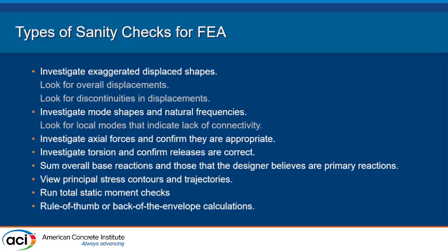Anyone who offsets a slab and has a beam frame member underneath it, there is a chord force that develops, axial force in your beam and your slab. And if you just pulled the bending moments out of that beam frame member, you would not have the correct bending moment that you're designing for. So if you did a simple WL²/8 check, you'd say, oh, wait, that moment's not right. But when you accounted for the axial forces, you'd get it right. You'd have the right value.